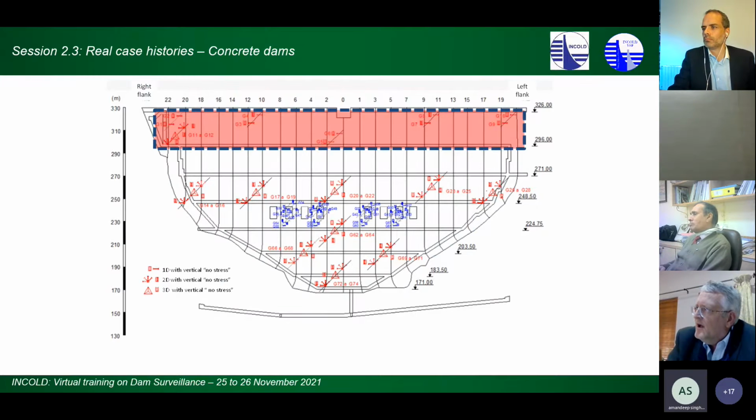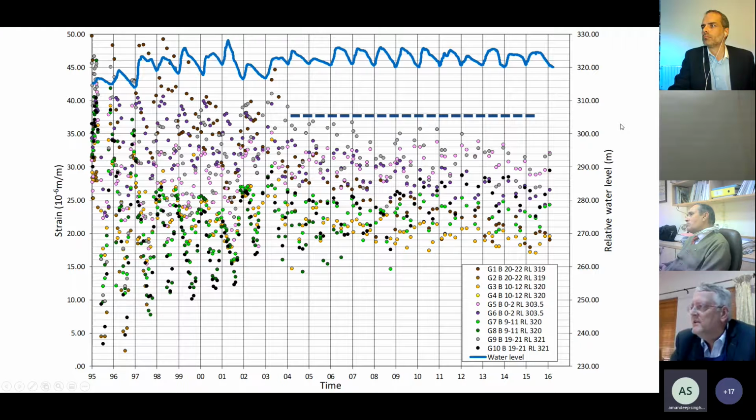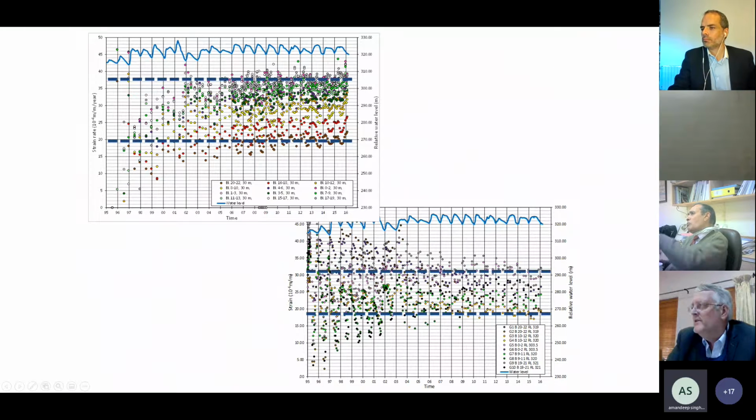All right. And if we just go and look at the top and we compare those, all right, you guys will also see that they are also less. But it's important that Carlson strain gauges have no opening on either side. They installed in the middle. So there's constraint from all sides. So if one actually goes and compares it, it's interesting to note that those rod extensometers on the one side, they actually extend from a gallery because that's where you take the readings.